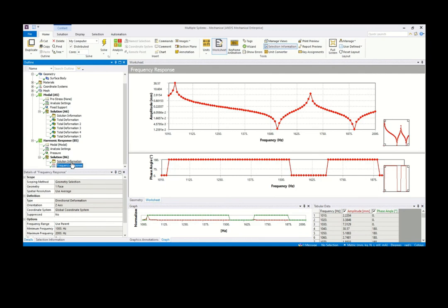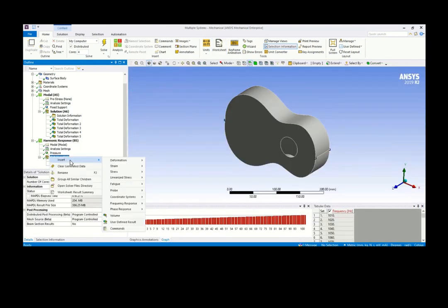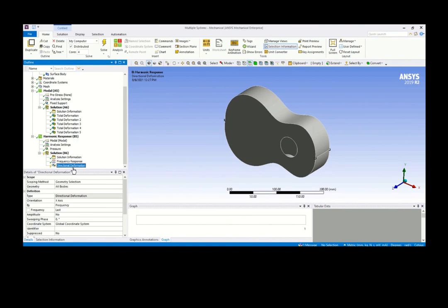In this particular case, you can also go into its animation. You can find, let's say, directional deformations in the z-axis, because we want to see the z-axis itself, for this face. And at what frequency? If you want to look into 1040, which is one of your data points, this number has to be one of your data points.